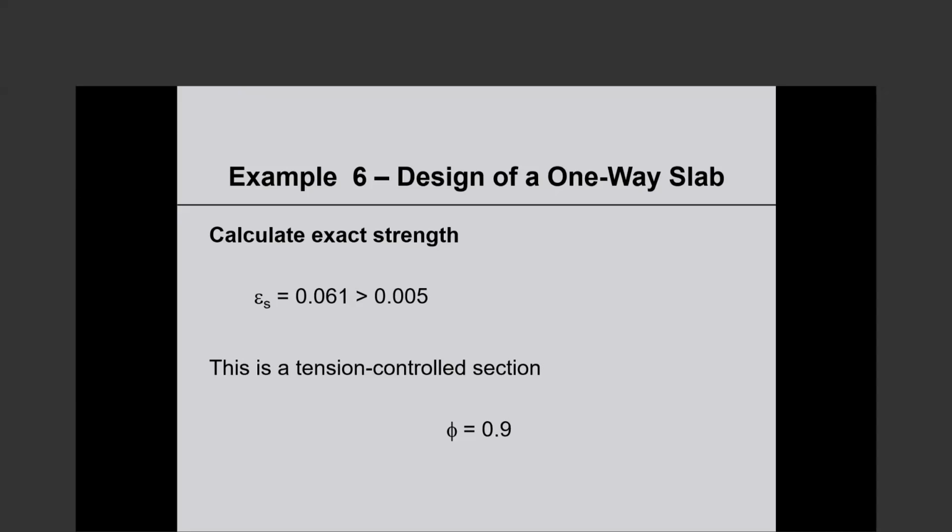So when the beam's capacity was checked, it was found that it was overstressed against lateral and vertical load combinations, implying that additional reinforcement in the negative section near the support is required to comply with the code. In that case, can we consider slab reinforcement up to 4 times the thickness of the slab?